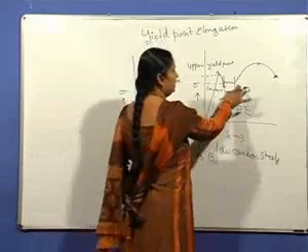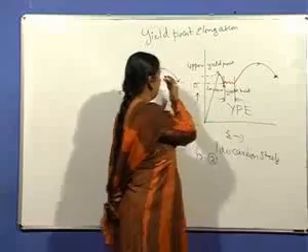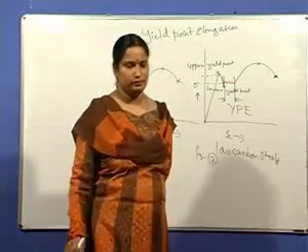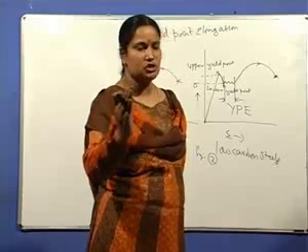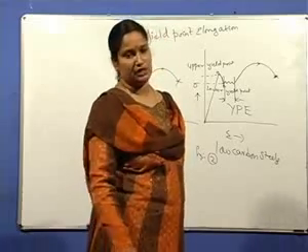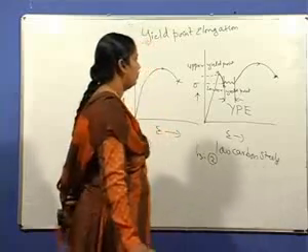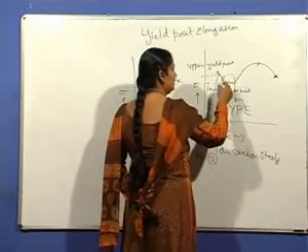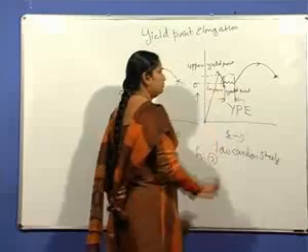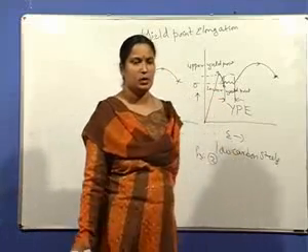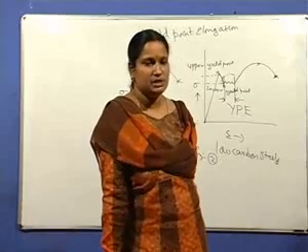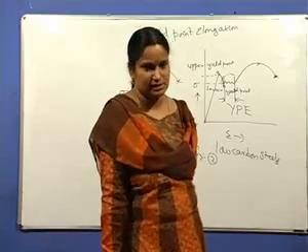Again, beyond this yield point elongation, the material follows the normal curve, undergoes strain hardening up to the maximum load, and then stress drops and undergoes fracture. But what is happening in this yield point elongation and why is this seen in this material, low carbon steel? What are the reasons for this? That will be discussed.